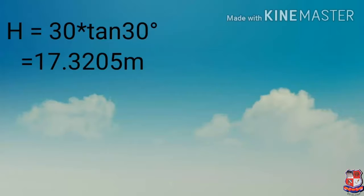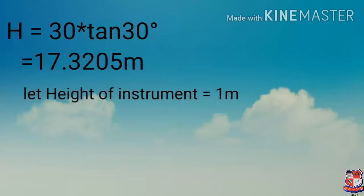So for the example, we got the height h equal to 17.3205 meters from the equation h is equal to d into tan theta. Suppose the instrument is around 1 meter above the base of the building, meaning the height of the instrument is equal to 1 meter.